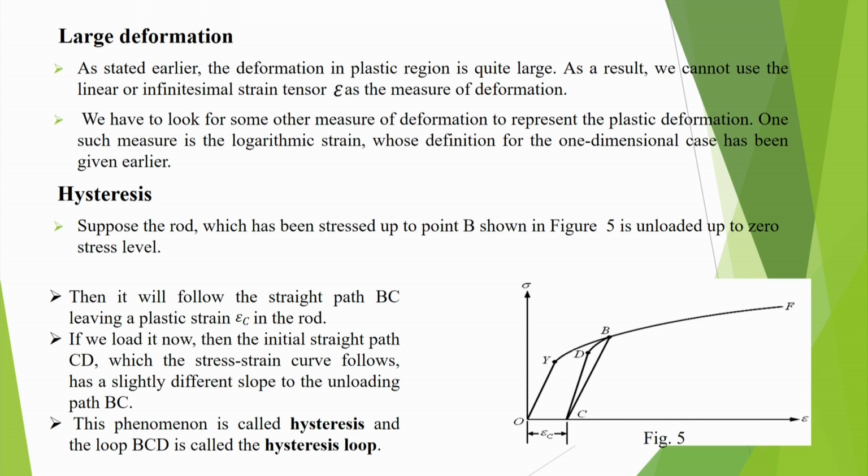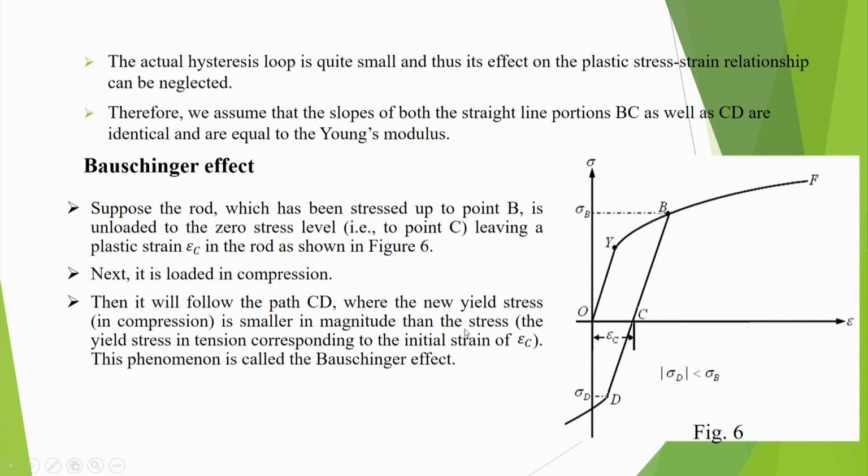That is why in most of the cases it is neglected. So, we do not talk much about the hysteresis here, but if we are studying the vibration behavior, hysteresis actually causes the damping. In those cases, this becomes very significant, how the vibrations are decaying. But since here strains are very high, the hysteresis is not important. So, the actual hysteresis loop is quite small, and thus its effect on the plastic stress strain relationship can be neglected.